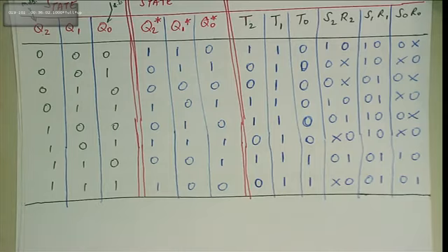Of course you've got the input X, but you're using only one flip-flop. It's either the SR or the JK, if I remember correctly. But with problem 1, you've got to use a mix of flip-flops. Let's say you end up with 3 flip-flops, and they asked you to use a JK and D combination. Out of the 3, you've got to do half and half, but obviously you can't divide 3 by 2.